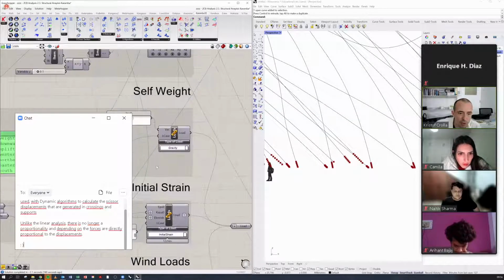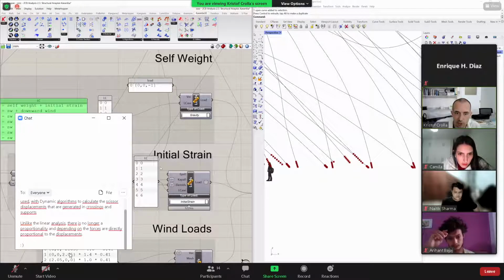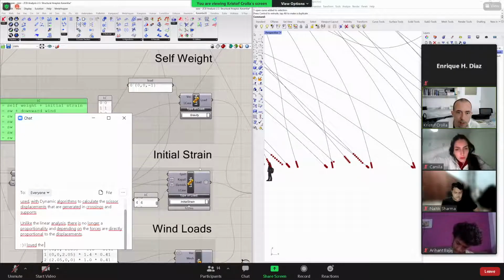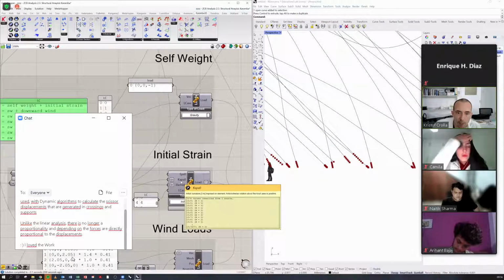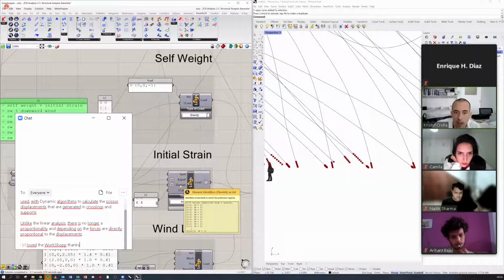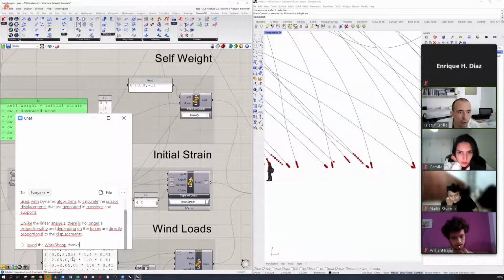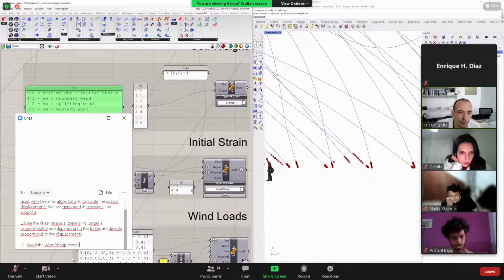Then we have the initial strain coming in. So initial strain is a similar load case scenario. So it's the same button, just pick initial strain here. We apply it to all the scenarios that we're working with. And here we need to have the curvature kappa in meter^-1, so per meter. And then we need to apply the element IDs as well to it. And those are the only 2 values that we need. So we need to calculate the curvature of our pieces.